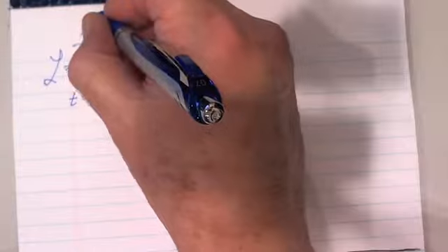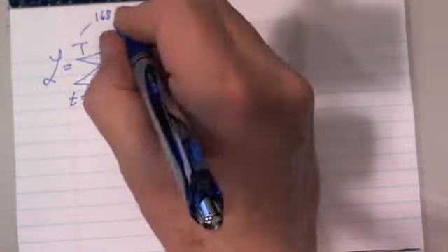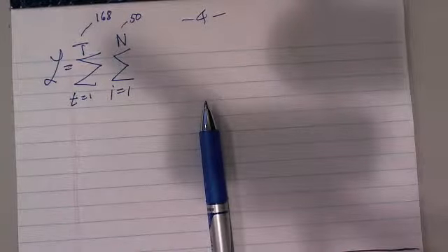Now remember that this could be like 1 week every hour, so 168, and I could have, let's say, a small number, 50 generator units. What would that be? That's 8,400. Okay, that's a lot of combinations. You can't sit down and enumerate them. A computer could, but you don't really want to do it that way.